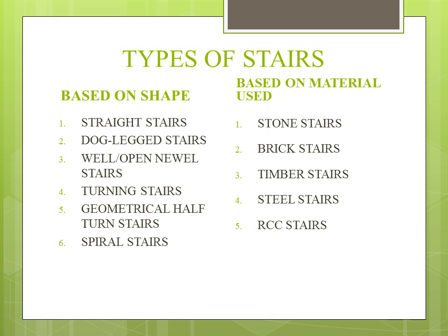Straight stairs are provided where the area is very narrow. It consists of mostly a single flight. Dog-leg stairs consist of two straight stairs with a 180-degree turn, and the well or open stairs is similar to dog-leg, but there is a gap which ranges between 0.5 to 1 meters.